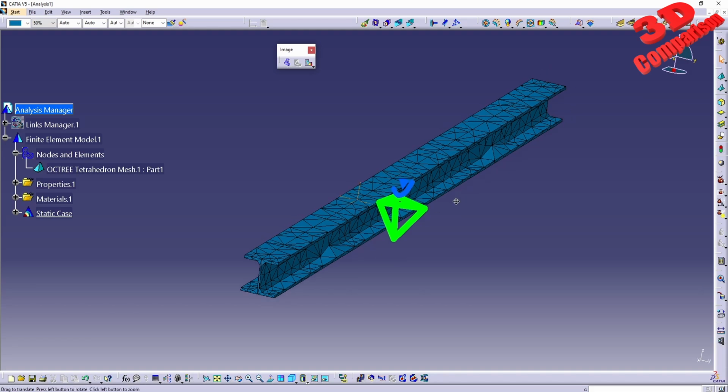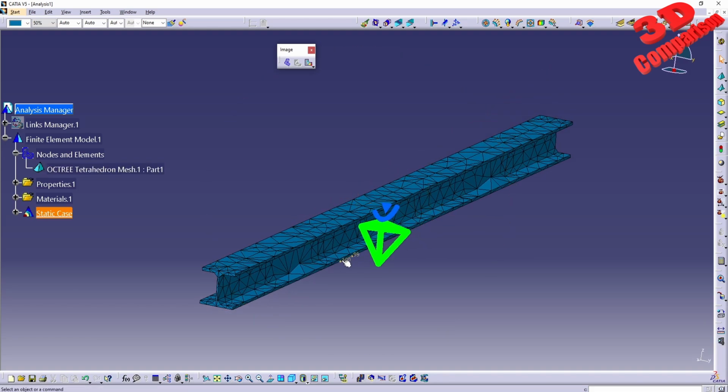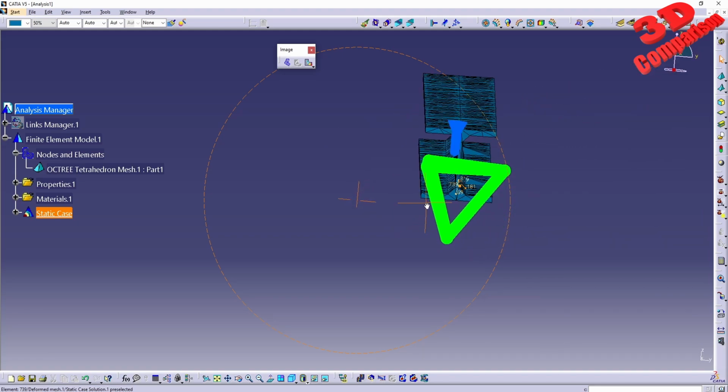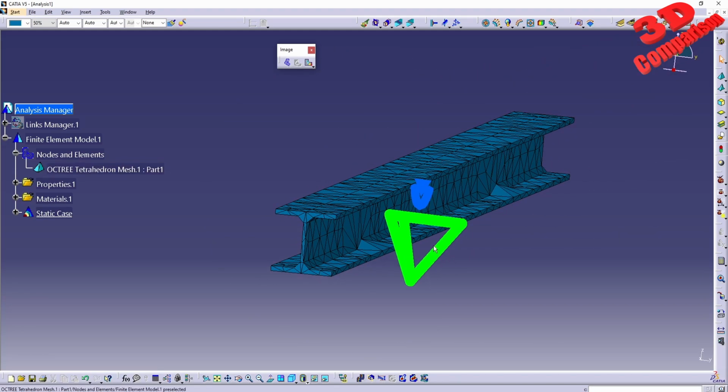Now, it's usually a good idea to make this smaller. For example, in this case, with those values, we see that the beam over here doesn't even follow the profile that we added. We had that radius of 10, and we see that during the remesh, this has been heavily deformed. But this will actually be the mesh used for the calculation.